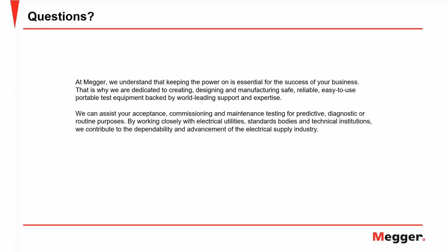Okay, so earlier in the presentation, Daniel talked about standards and the requirements for primary injection testing and what changed in 2017. NFPA 70 and the NEC both mandated that ground fault systems shall be tested by a primary injection process. Prior to this, it was left up to the contractor or the manufacturer of the equipment on how to do these tests.